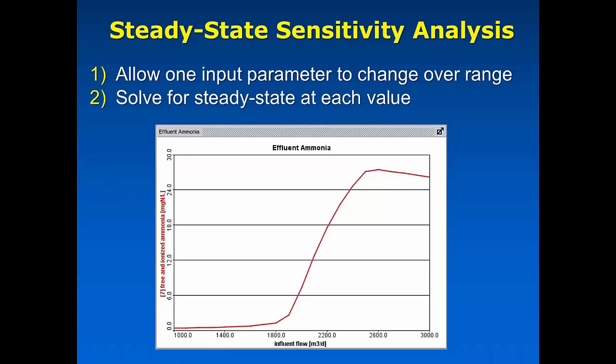Okay, so coming back to talk about those a little bit in more detail, and we're going to run some demonstrations. Essentially, in the step analysis, we are going to pick what we want to happen across the bottom axis on this graph here, on this x-axis. Now, normally in GPSX, you're used to seeing time on this axis. However, now when you're running a sensitivity analysis, we want the variable of interest, the one that you're changing, that input, to be the independent variable.